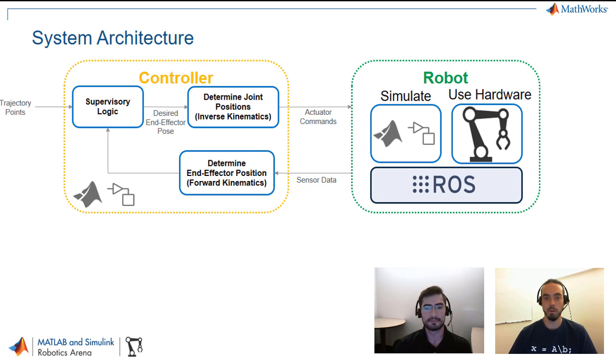So forward kinematics is going from your joint space to the physical position in 3D of the robot. And then inverse kinematics is a tougher problem, which is the opposite. If you want your robot to be in a specific position and orientation in the world, then how do you position all your actuators? So I guess we're gonna start looking at that soon.